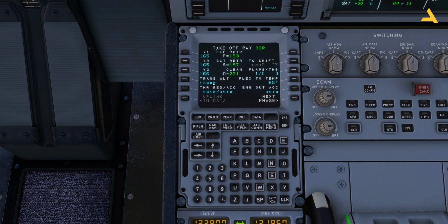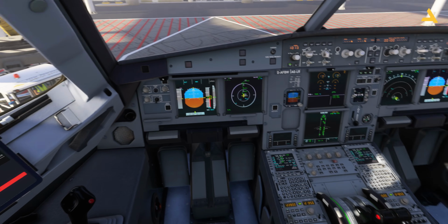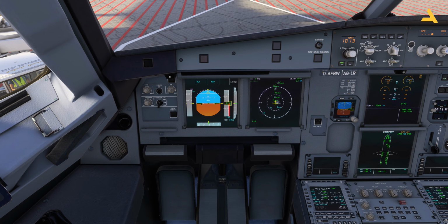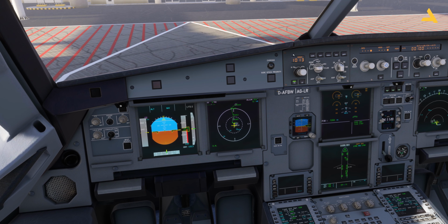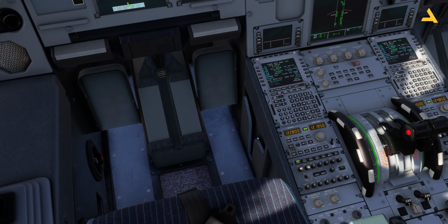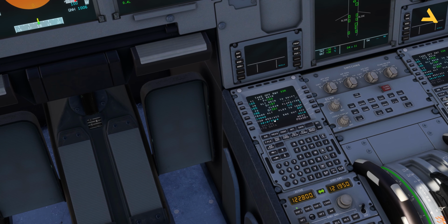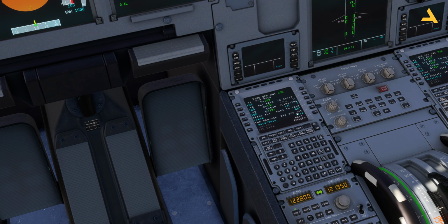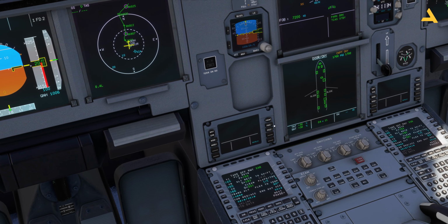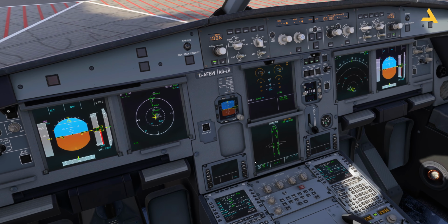Now you can see the thrust reduction altitude is 3000 because let me just show you. Riyadh is already, I haven't adjusted the altimeter for pressure. Now we get the current readings. It's 2000 feet above the sea level, so that's why if you add 1000 to it, it's almost like 3010. And this is the engine out and acceleration altitude. It's there, and that's it. So everything is good now.